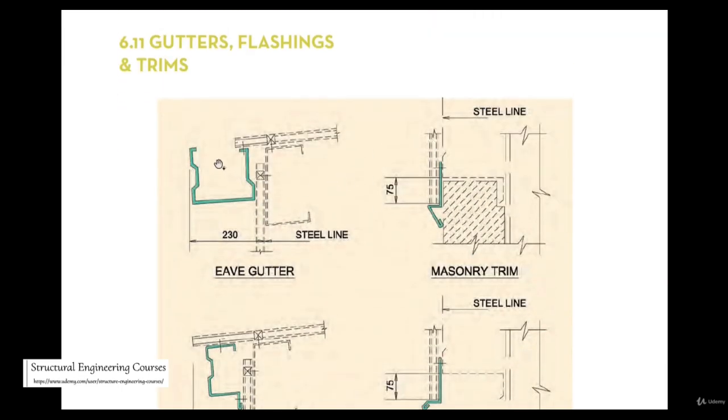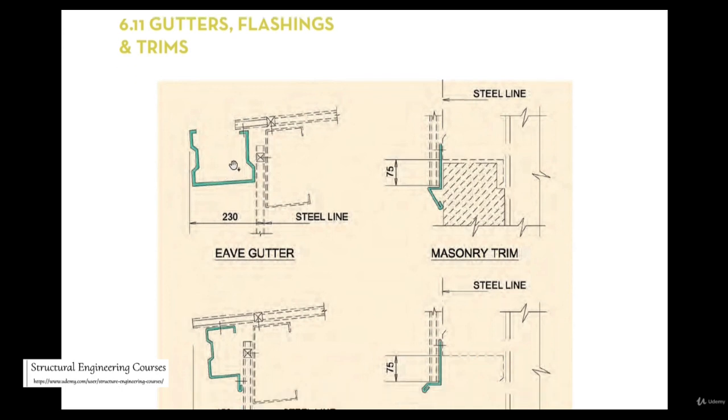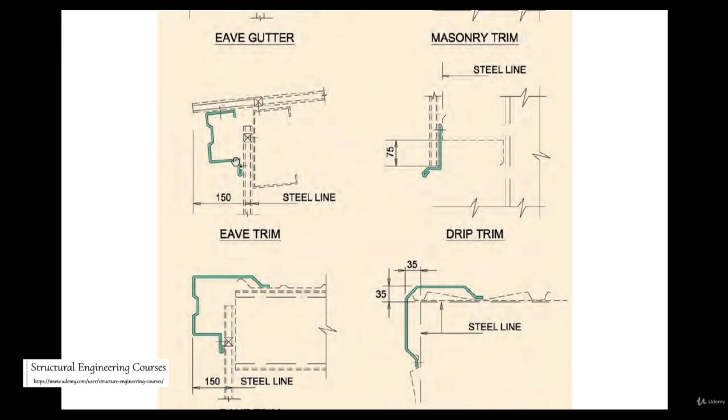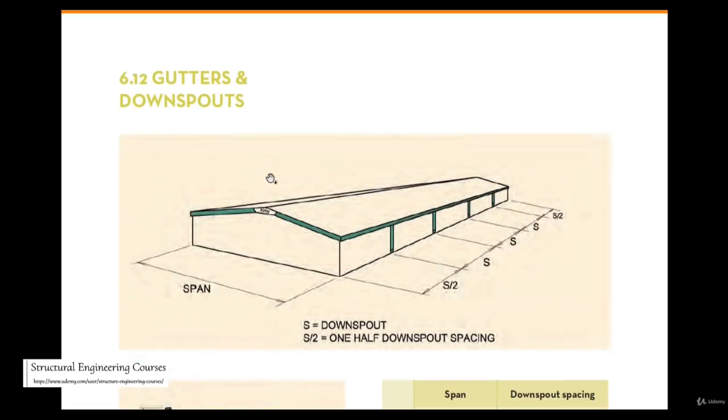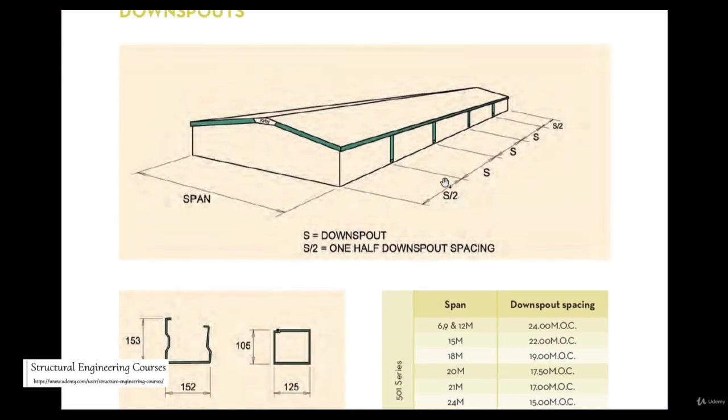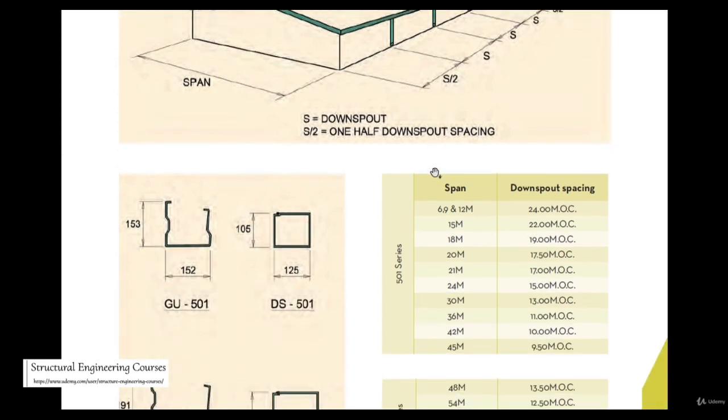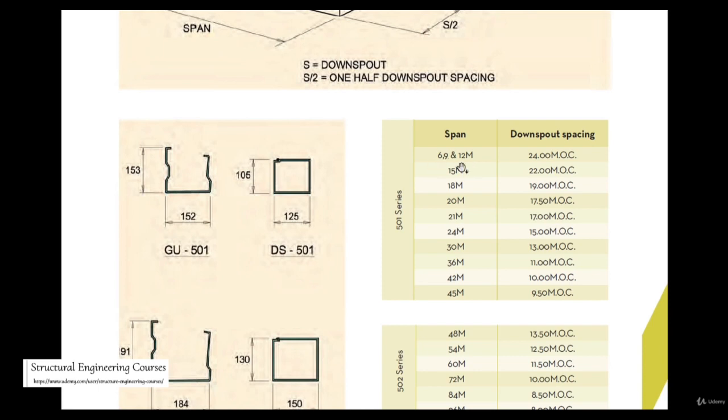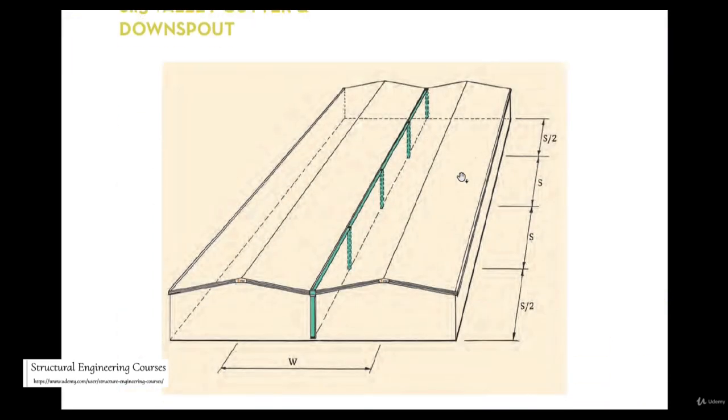This is called a gutter. Initially we were discussing the rainwater exit. So this is a typical section showing the gutter arrangement. Basically the rainwater comes here, and from this it gets collected into the downspout pipes. Here they had given the possible location of the downspouts. They had drawn a 4 downspout arrangement here, and they had given the typical downspout spacing also.